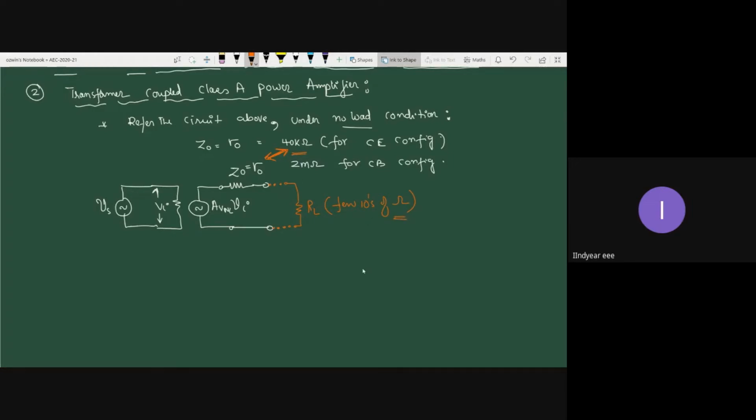That's the reason there exists a huge impedance mismatch in the series fed class A power amplifier. As a consequence, the conversion efficiency drops, because only a small part of the power is supplied from source to the load. Hence, you can observe dipping efficiency.